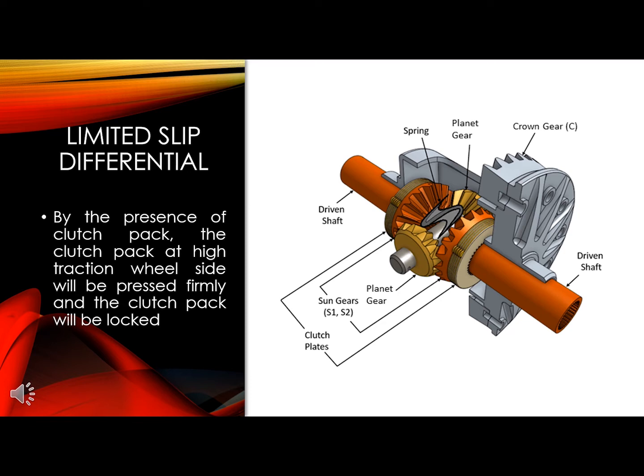Friction discs with internal teeth are locked with the side gear, so the friction disc and the side gear that connects to the axle shaft will move together. Steel plates have external pads and are made to fit the case groove, and they are installed on the friction discs in an interlaced layout for a few layers in the casing.